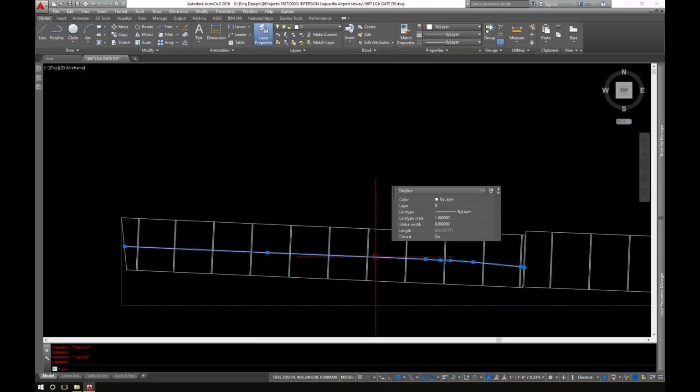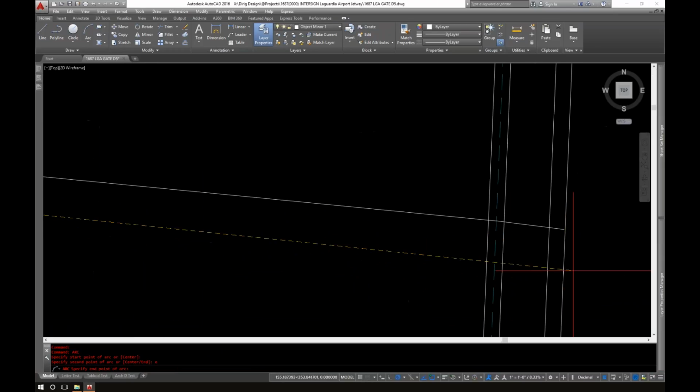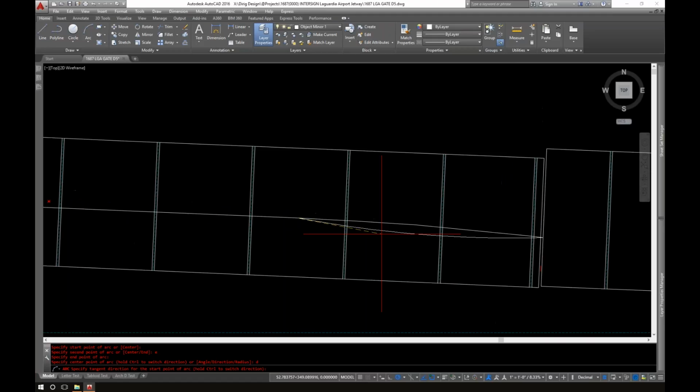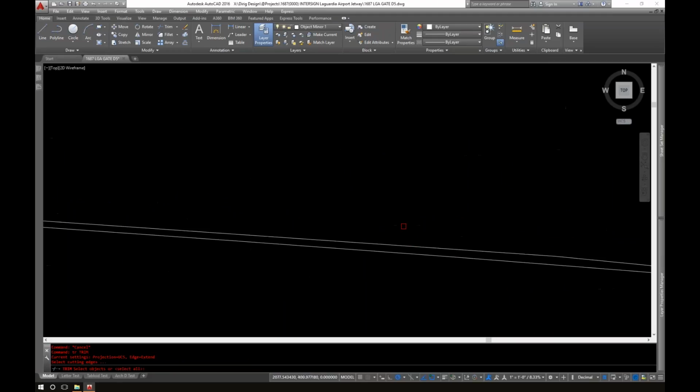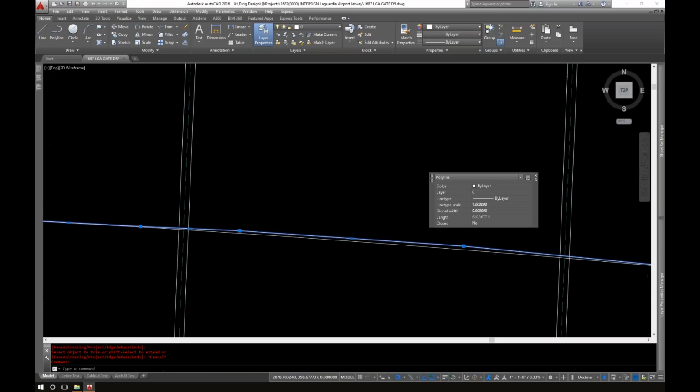But the last thing I want to do is just draw an arc from where this starts the curve, and I'm going to hit E for end to here and D for direction. And that's going to give us pretty close. Again, this does not have to be perfect. It was really just to get the visual.